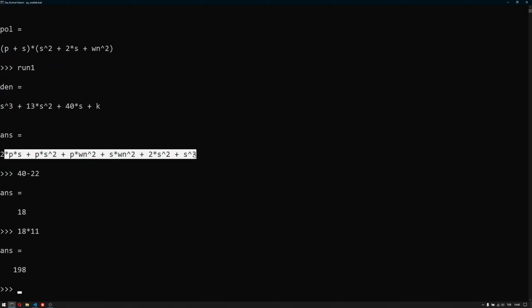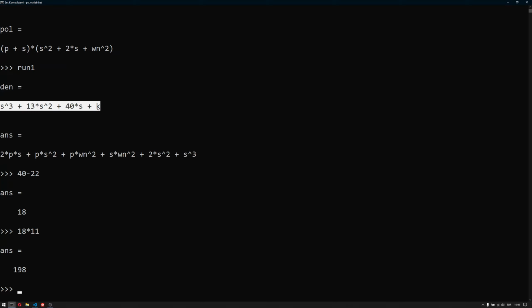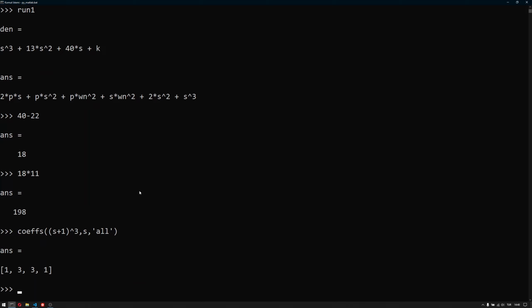We're basically modeling a polynomial, equating it to the actual polynomial, and hoping that it is possible to model it like that. So we could have also come up with maybe 2 or 3 poles, multiplied them and tried to equate them to this, but that would not be possible. So for example, let's take the coefficients of (s+1) cubed, because these are 3 poles that might be a choice for us. You can see that the s cubed term should be equal to 1. We satisfy that.